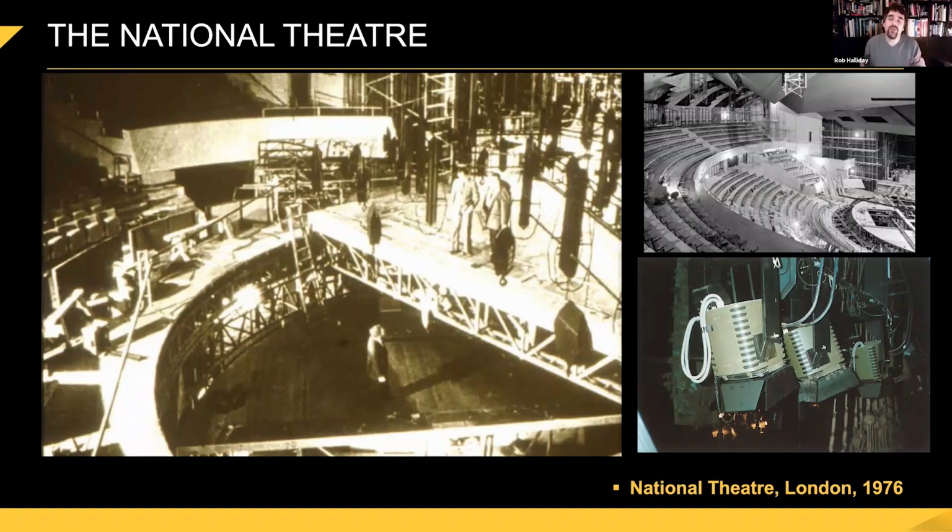So the theory was they would put in enough lights that there'd be a sort of comprehensive cover rig, and then a series of specials that you could have per show, and then a very few lights you could refocus. But then over the stage, which was incredibly high and hard to access, they put in a rig of moving lights, which were 2K Strand Fresnels with a motorized yoke made by either Pani or Technic, one of the German Austrian companies who were a bit ahead of the game in equipping German theatres. And that was 1976.